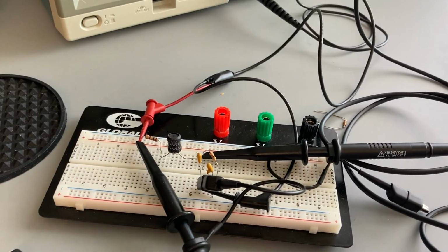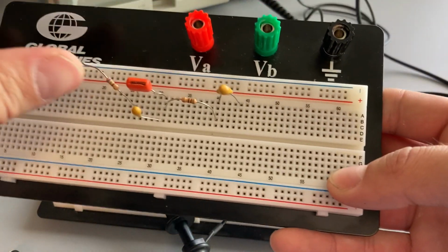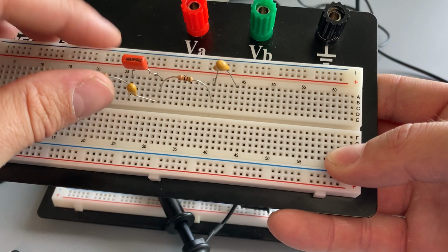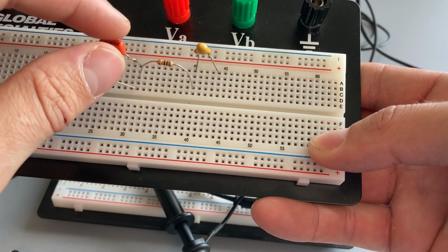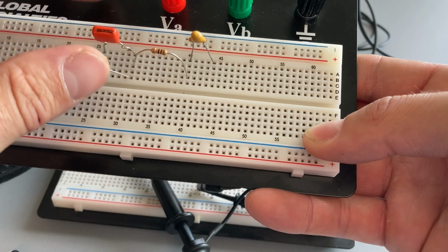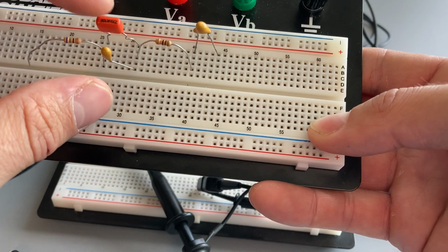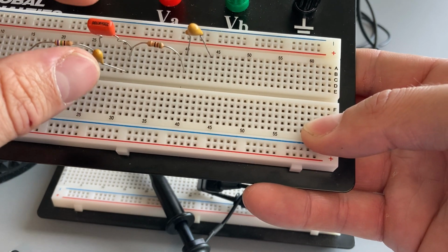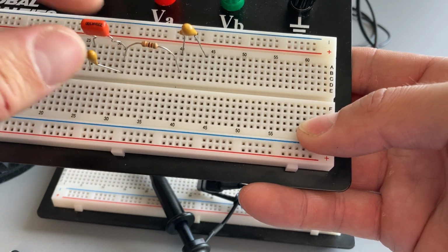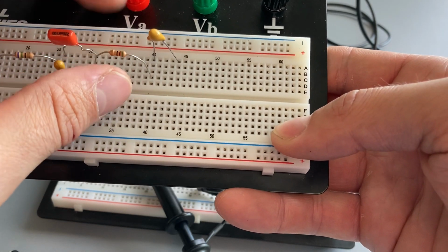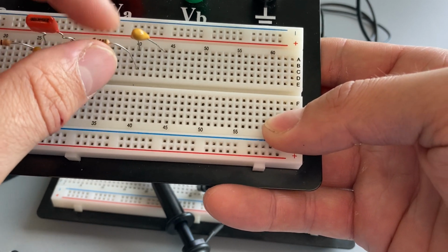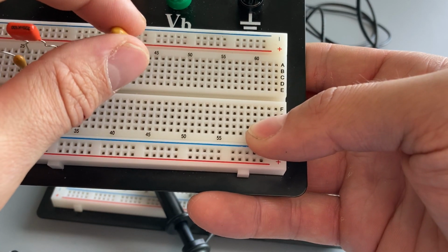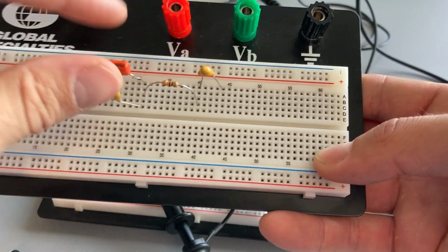So I went from this circuit to this circuit here. I have my 73 ohm resistor. I have two capacitors in parallel that roughly equal 3.6 microfarad. I think this was 3.3 and then this was 0.4, so, other way around. And then I have my load, my original load, which is the 51 ohm resistor and a 1 microfarad capacitor.